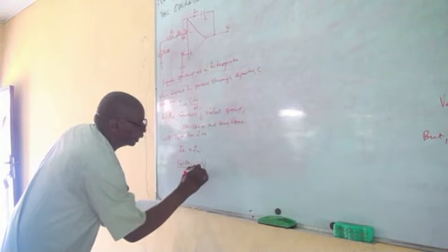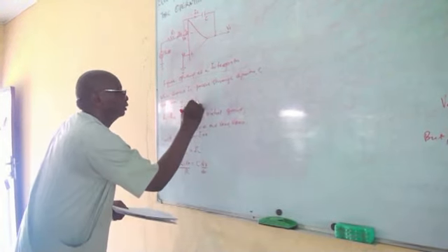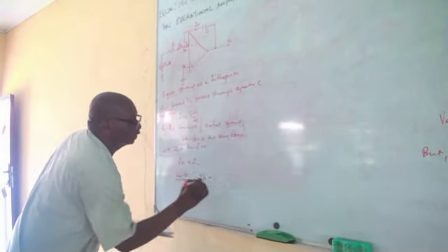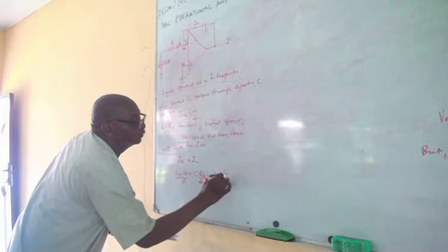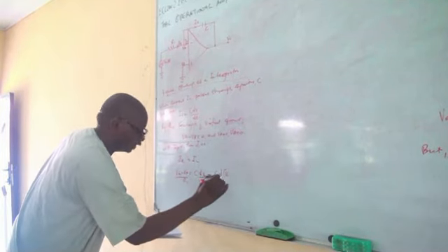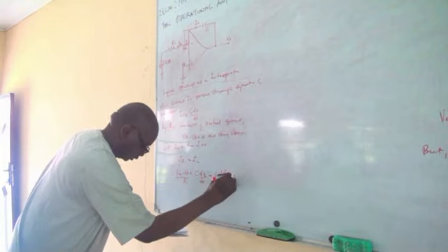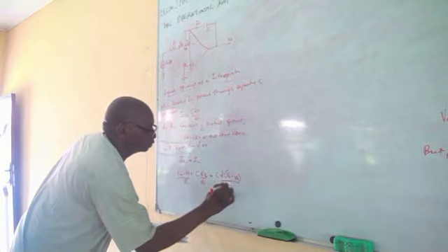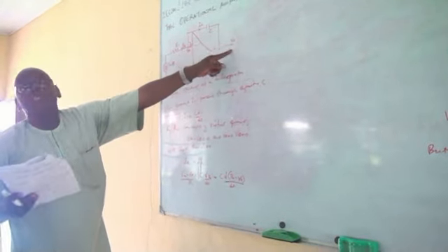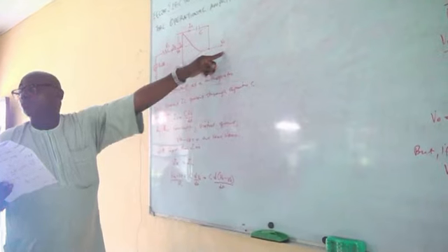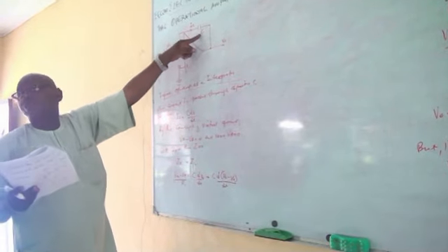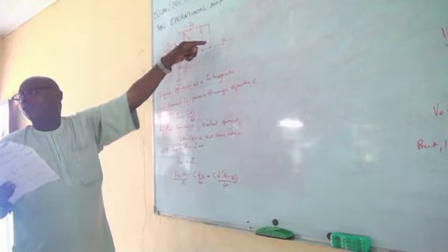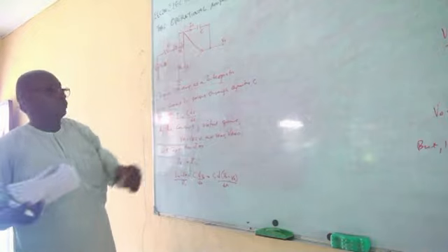So the V here could be the V differential, which equals C d(VA minus Vout) over dt. VA minus Vout is to get the current that's passing through the capacitor. When it was a resistor, it was VA minus V naught, is it not? Yes. That's what we're doing now.